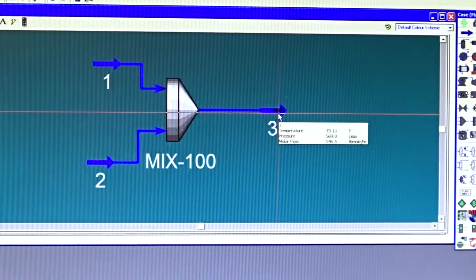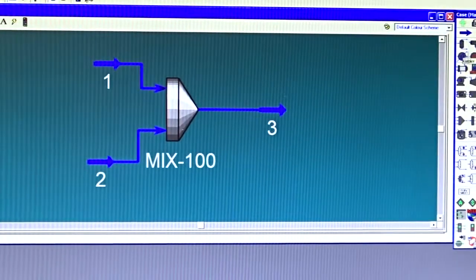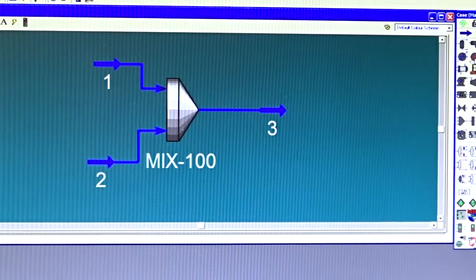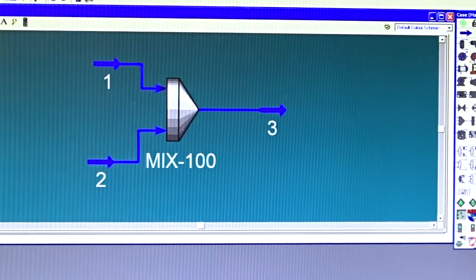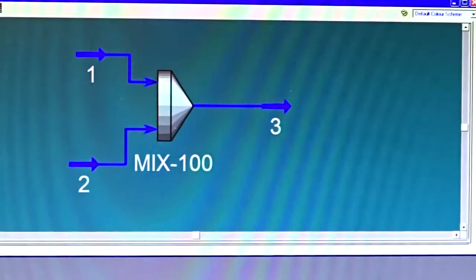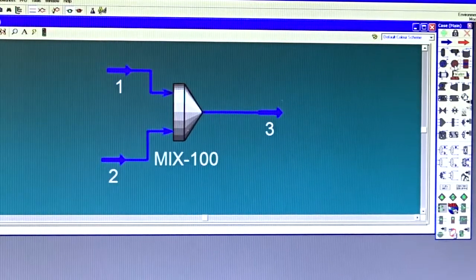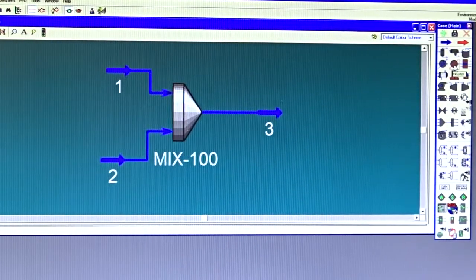How do we achieve this? We can achieve this in many ways in HYSYS. I can use a heater. What is a heater in HYSYS? It's a heat exchanger, but without knowing the utility side. It just calculates the heat duty of this exchange process, heat transfer process.